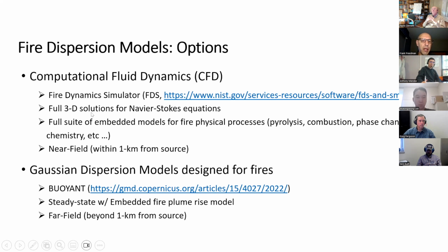It's for the near field computational fluid dynamics. It's a very literal type of approach in following the 3D Navier-Stokes equations. It's on a 3D grid. So that has computational cost when modeling. So it's not possible with CFD to model a very large downwind distance. So we want to apply that to the near field, maybe the nearest kilometer from the source.